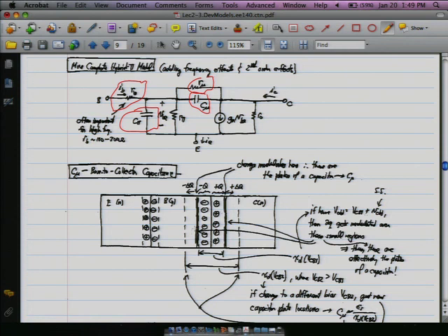And so the plates of that cap are the edges of the depletion region. As we modulate it, those values for C are going to change. And that's what's coming out in this figure. So over here, this is our C mu that we're talking about, and then over here between the base and the emitter is our C pi.